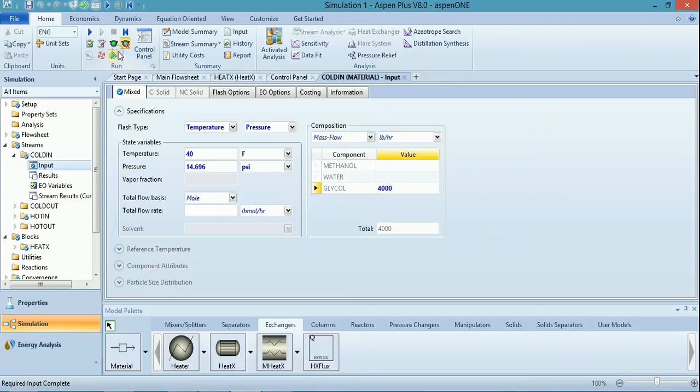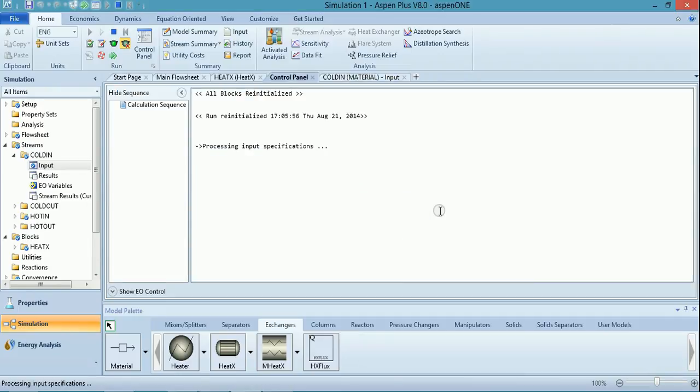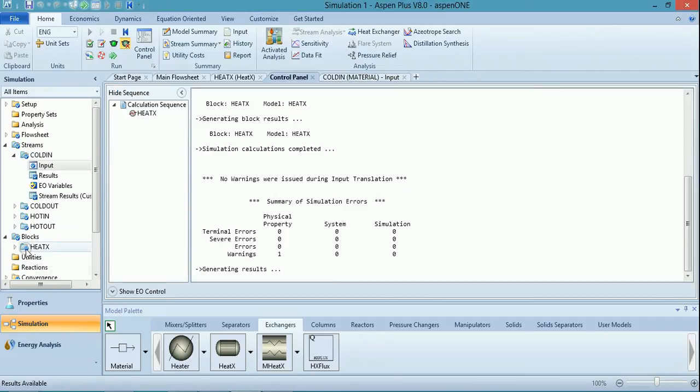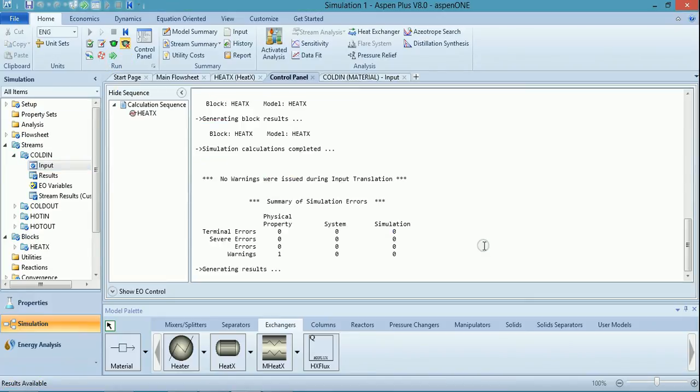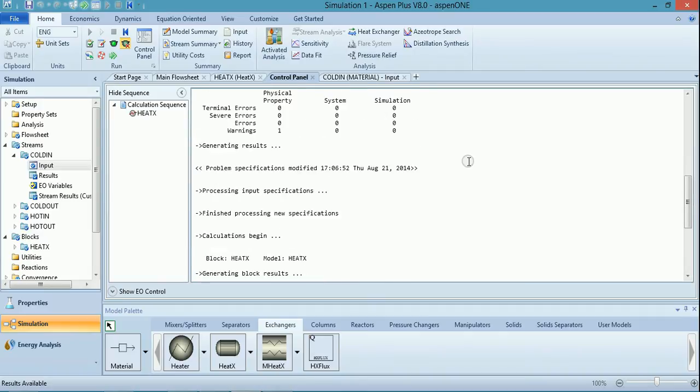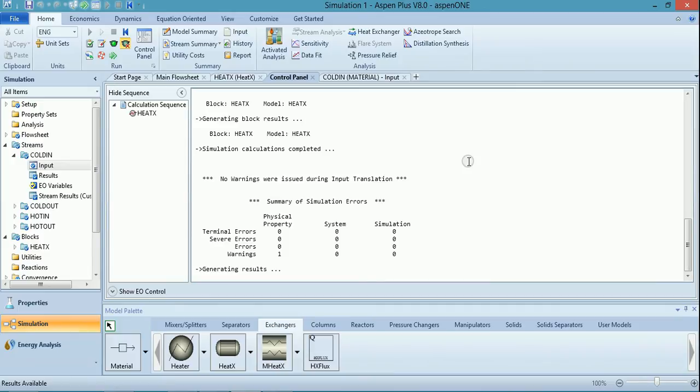So how can we do that? By normal logic, you know that if we increase the flow rate of the coolant, then temperature crossover might not occur. So cold stream inlet from 400, let's change it to 4000. Right, just as a wild guess. I again press next, run the simulation. Yeah, it executed. You can see it's blue right now. But we do not want to waste any coolant because obviously, they are expensive. You cannot waste them. So in an ideal situation, we need to optimize this. This optimization will be carried out by trial and error method.